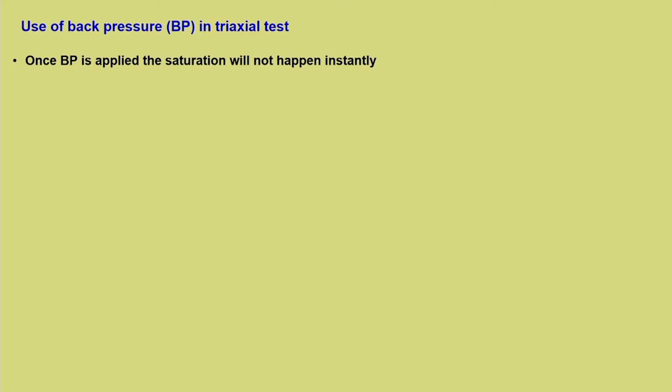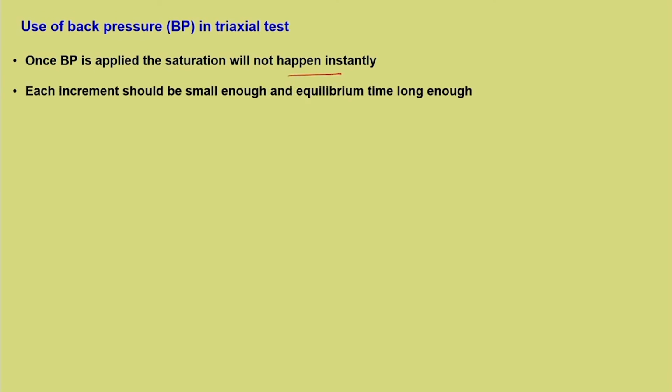When a load is acted upon into the soil, we say that immediately the water captures all the load. Yes, this is true, but there is a bit of time lag by the time it delegates to the entire soil sample. So, when the back pressure is applied, the saturation will not happen instantly, it is not an instant response. Just because of this, each increment should be small enough and equilibrium time should be long enough. So, we need to wait for some time and the increment has to be small.